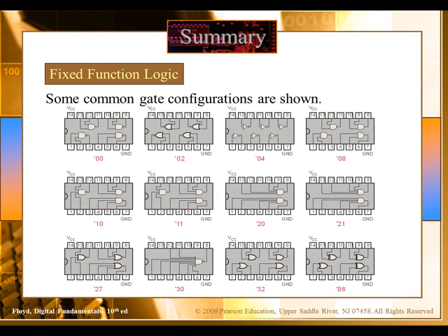Now, if you look at the ICs, look carefully, something is very common here. Look at pin 14. It's written VCC. That means it should be connected to the voltage 5. And pin 7 should be connected to the ground. I'm saying the common ground, which is voltage 0. These 2 pins must be connected like this to make the IC work, to operate the IC.